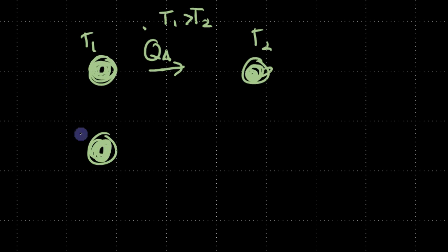The way I can do it is if I cover it with a black paint, then it's actually going to emit more light, because there's also internal reflections happening inside. So more light would be able to escape and go into the T2 ball. So more light would be emitted due to the change in color. This has to do with the change in emissivity.